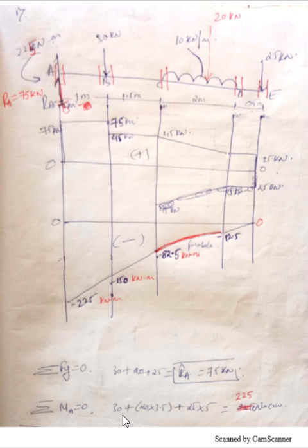So finally the moment because of the summation of all three forces, I'm going to get as 225 kilonewton meter. This will be acting clockwise, but the reaction will be anti-clockwise, but the value is going to be the same, that is 225 kilonewton meter.